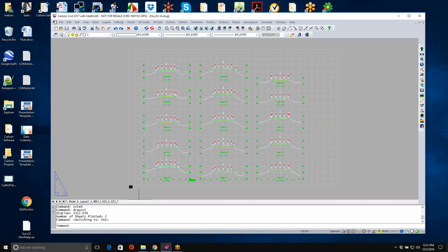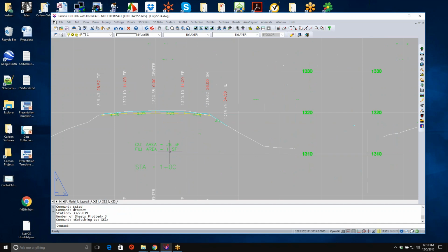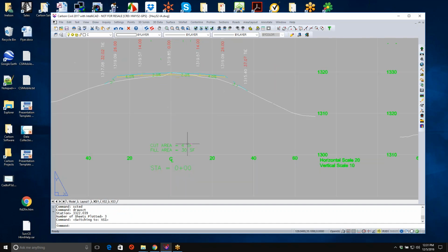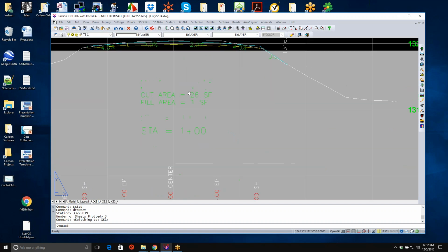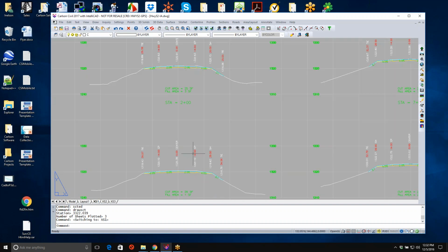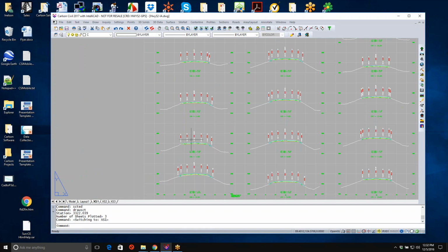So if we take a look at this in cross-section sheet number 1, you can see that I've labeled the sections to start in from the sheet, and so what we'll have in here are the offset values listed here on a per grid basis, the end areas that are established for me, and again here's where we can see we have the different offsets, elevations, offsets and elevations, and then feature codes for labeling and even for stakeout purposes.